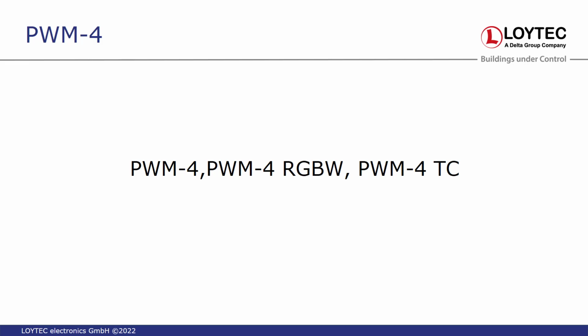Thanks, Pierre. Just for you to know, we have a project with RGB white, and finally we bought the PWM4. We put the RGB white strip, and it works really fine. The only issue is that we have 4 DALI addresses, and we have to combine all 4 addresses to get the correct color. So if you want pink, you have to choose some percentage of red and blue, for example.